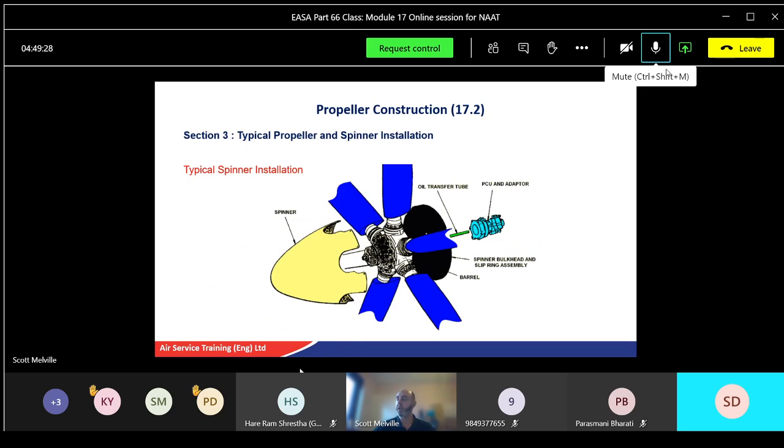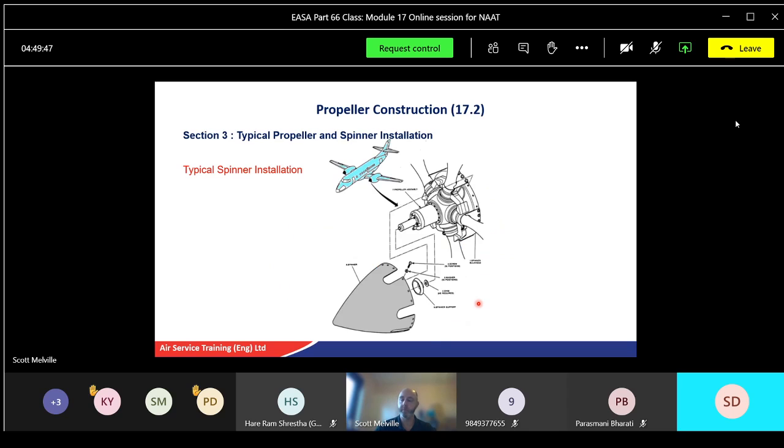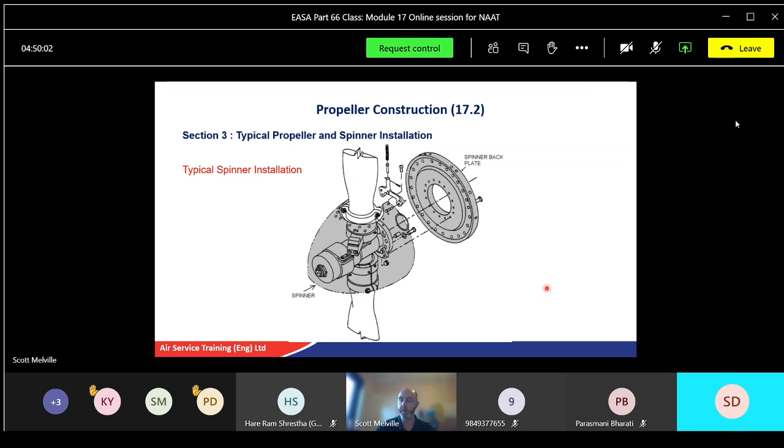So, a basic exploded diagram again, there's your spinner. It is possible to potentially put a spinner on at different positions around the hub assembly, but normally there will be a locating pin or locating dowel which will keep it in the same place. Some do, some don't. Again, just an exploded view of where it will be: some sort of support, and then the casing itself will just locate onto maybe drillings around the back plate here. Just various different ways of doing it.